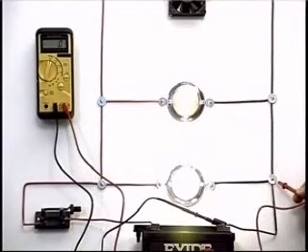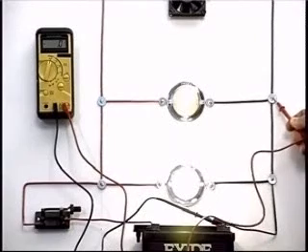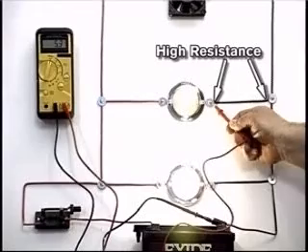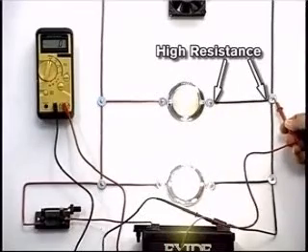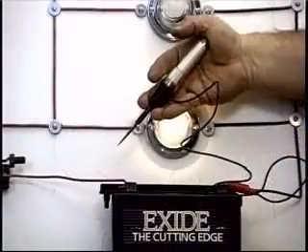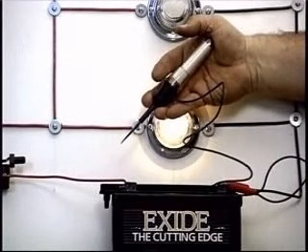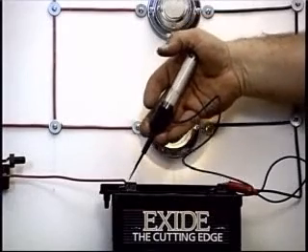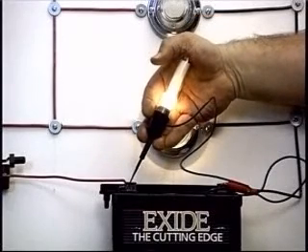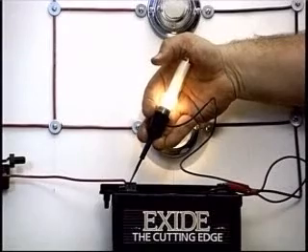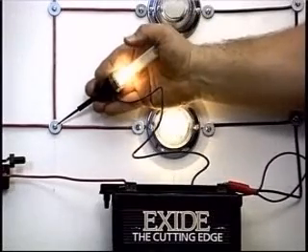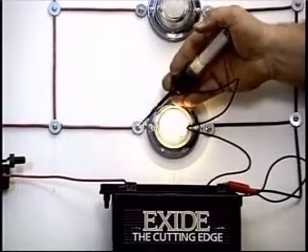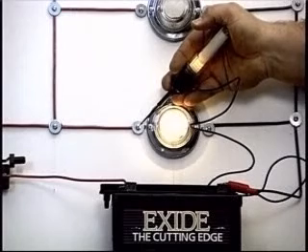Voltage readings taken after the circuit passes through the load should be zero, since this is the ground side of the circuit. If voltage is present, a significant resistance exists in the ground circuit back to the battery. If a voltmeter is not available, a test light can be used in the same way as a voltmeter, however with a lesser degree of accuracy. After testing and observing the brightness of the bulb when connecting directly across the battery, proceed with testing. A brilliant bulb is a good indication of a high voltage reading, and a dim glow from the bulb is an indicator of a low reading.